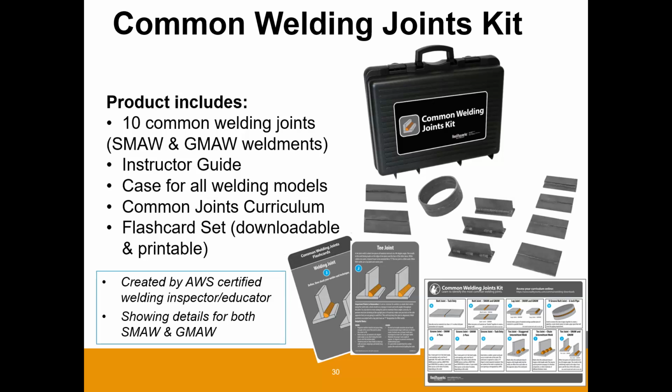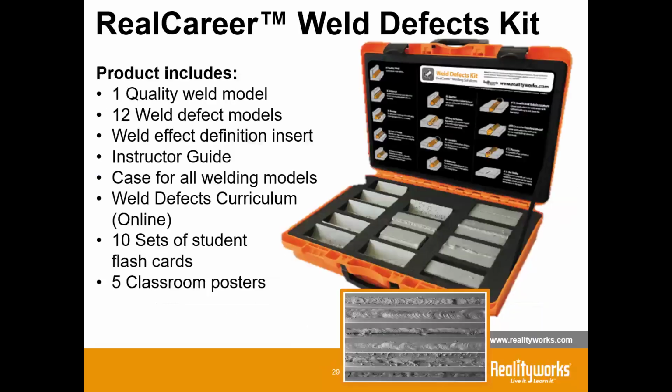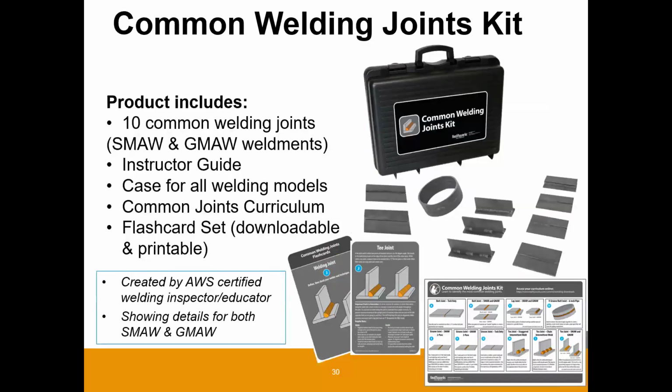And then in this case, if they did it incorrectly after the weld, they can look and say, what is the problem? Is it undercutting? Is it overlap? Is it too much spatter? All those different things can then be taught: okay, yep, it's your technique. You need to raise your hand up higher. You need to go a little slower. You need to be farther away or closer to the weld. And then they learn proper welding through that.